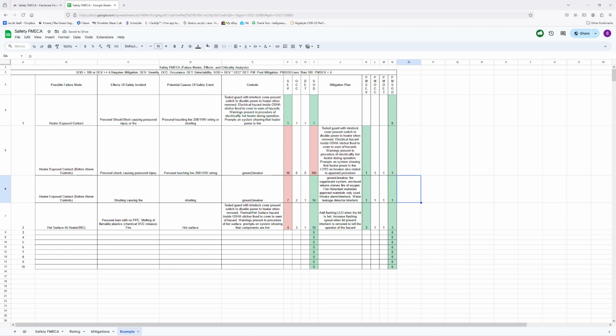So even if the breaker doesn't trip and it's still supplying 2,000 watts of power into this fire, because fire retardants will only put themselves out if the energy is removed. So let's say the energy is not removed, the fire is still going. Let's say it doesn't short. Then the fire suppression system would put it out, or the enclosed volume will starve the fire of fuel.